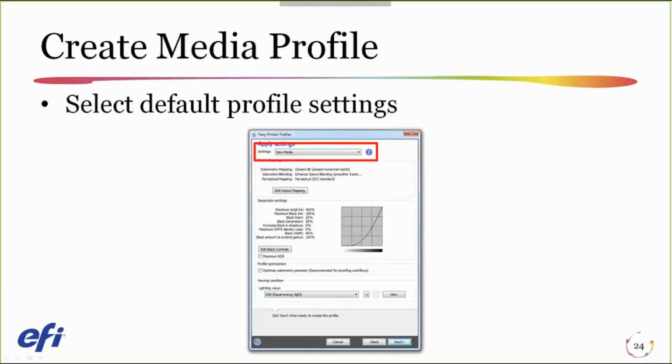Next down is the Gamut mapping area. For most users, you leave those as the defaults. The only option you might want to consider is the following. You might want to change the Perceptual mapping option. We have an option that will increase shadow detail if you go into that option.